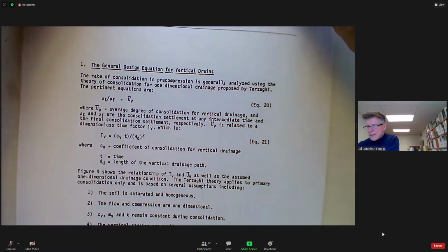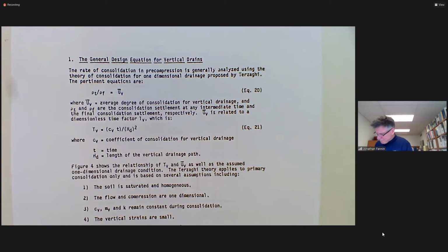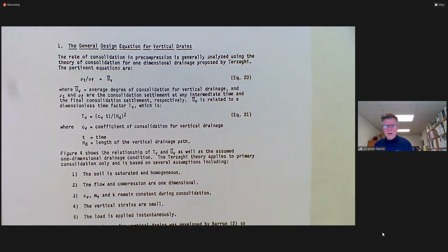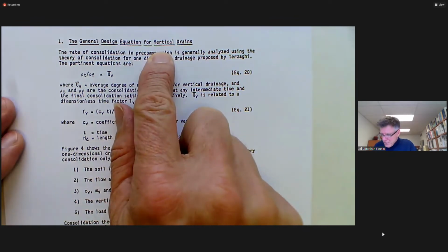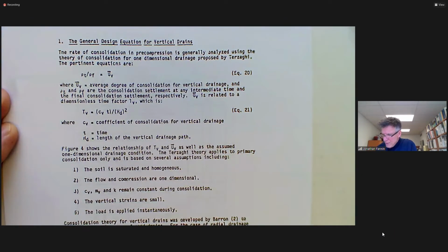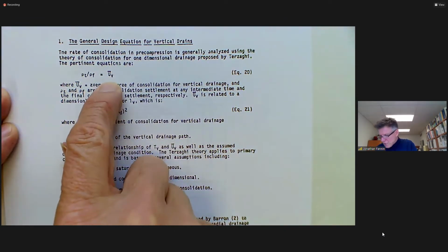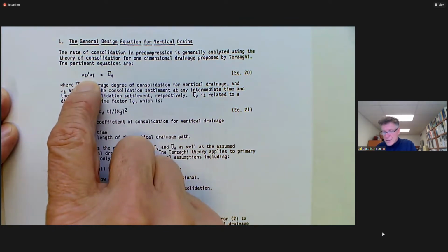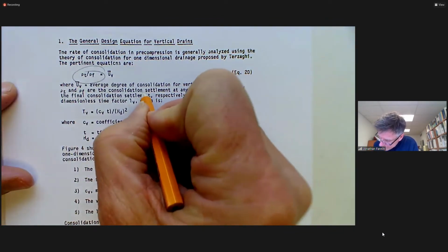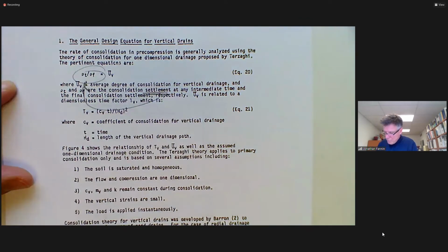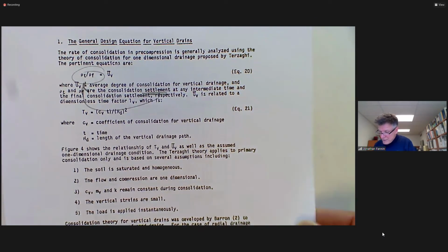Okay, and the math is going to be a derivation of an expression. It follows over the page. I wanted to remember that learning objective of how far back do we go? The general approach for vertical drains, and it's set out here, was picking up on Terzaghi's appreciation for time factors governing consolidation or degree of consolidation. There it is again, captured with regard to settlements. But it could be done with regard to excess pore pressures, and that in fact is the derivation that we're going to look at just over the page.